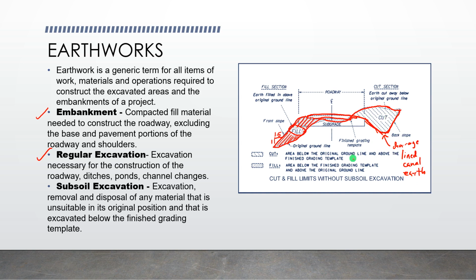on the right side of the roadway, so that when it rains, the runoff of rainfall goes to the sides, and this area here will serve as drainage for the roadway, so that the water will not stay in the middle of the roadway. So this area here that is needed in calculating the volume for excavation is what you call the cut. So this is cut here.